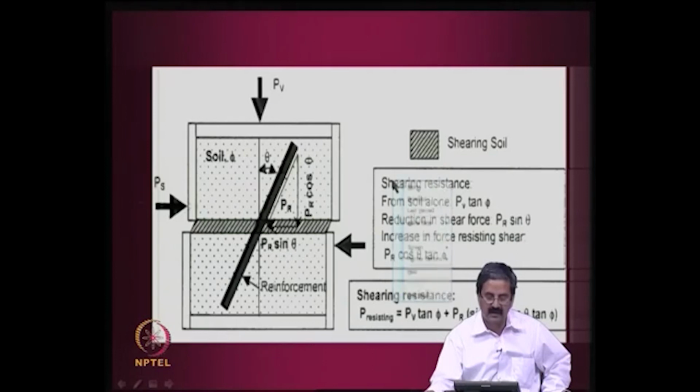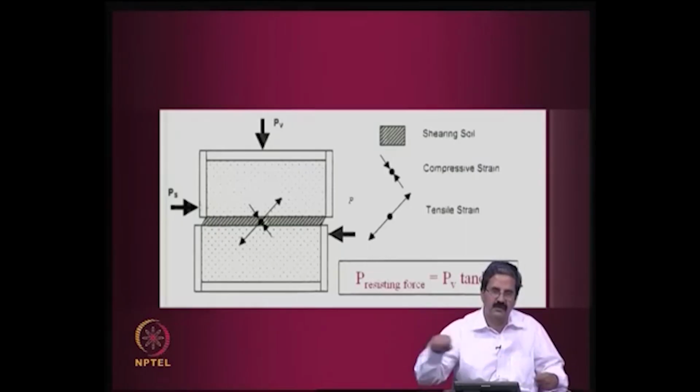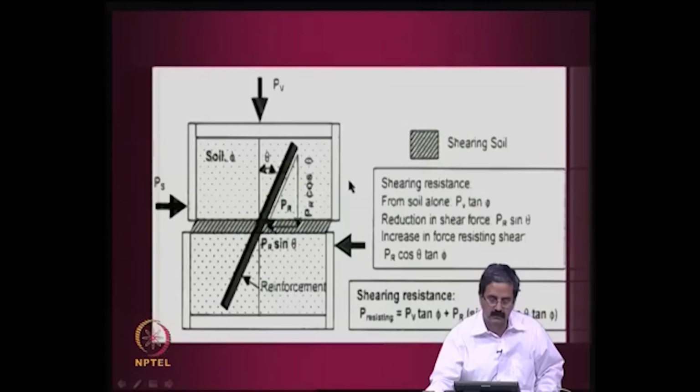The way that we put it, we are trying to put it in the direction of tensile strains a little bit, because if you want to take advantage of the reinforcement, you should put it in the direction of tensile force. So, I am putting it in this direction, and this is that angle, whatever.